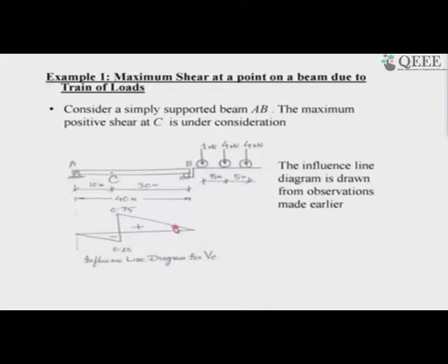The gaining overall means if my wheel load system moves from right to left, the quantity goes on increasing as the slope of the curve from right to left is actually increasing. So, that means if I have 2 wheel loads, if I move from here to here and both of them are in the positive direction, definitely I am going to be a gainer. So, definitely my positive shear will be increasing at this section.